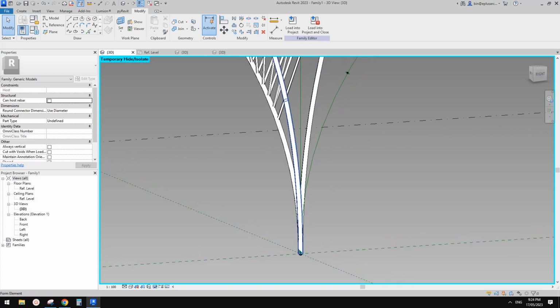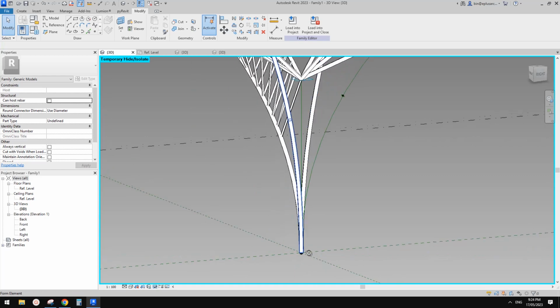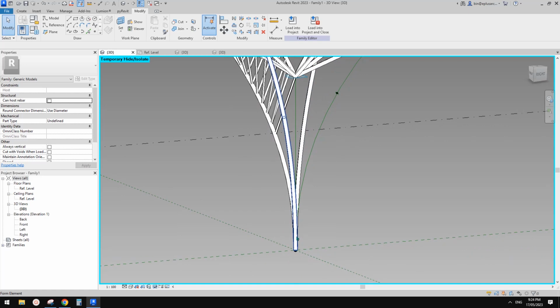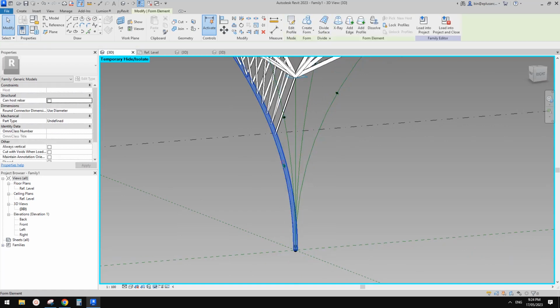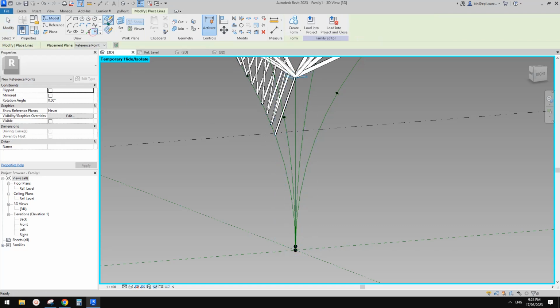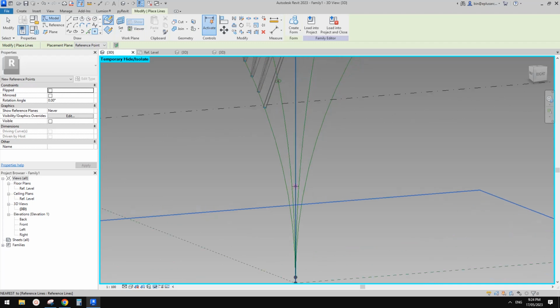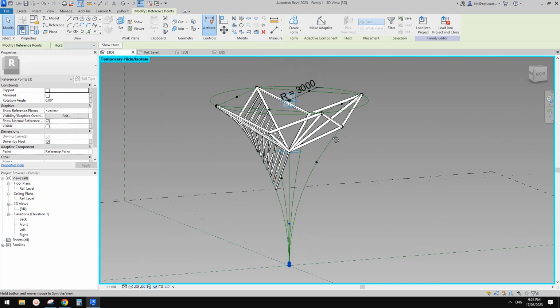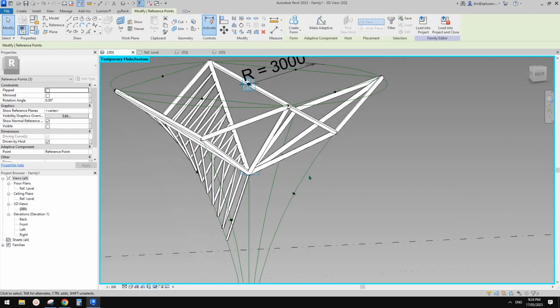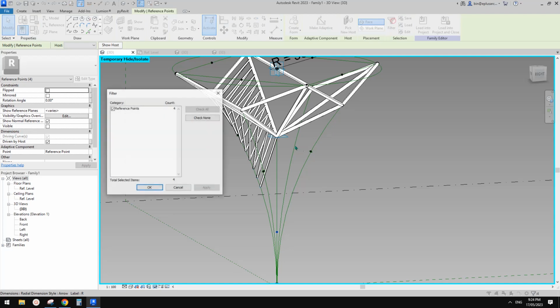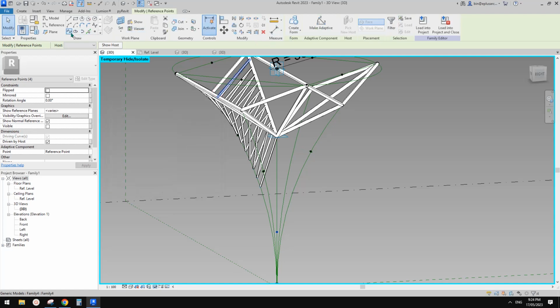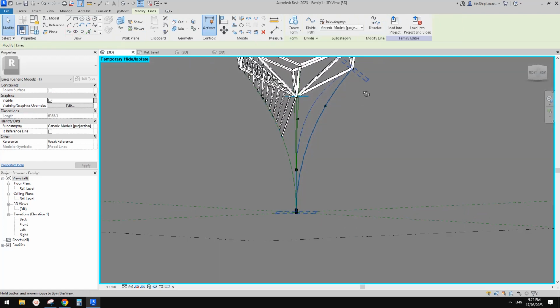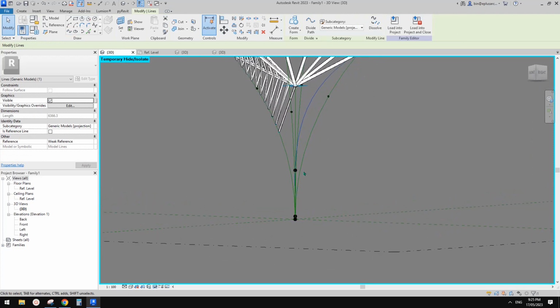So currently we have 2 points here which are very close to each other. So maybe, hang on, I'll HH. Okay, so let me try to place another point slightly higher here. Okay, so now we have 1, 2, Control select this one, and also another Control select this one. So we have four points. Okay, selected. Let's try this one. So spline through points. Yes, I think this will be better.